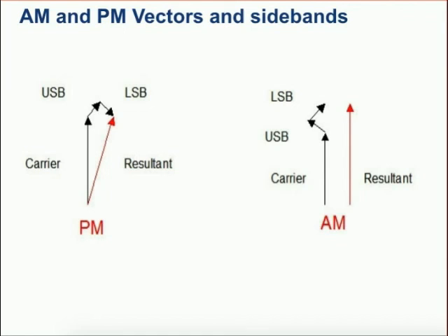It involves putting a carrier into the amplifier, the level that it's going to be operated at, and then measuring the noise in the difference of the phase between the input and the output. So this takes into account all noise sources, both the small noise that would be present in the absence of a carrier and also any noise modulation of the carrier itself.